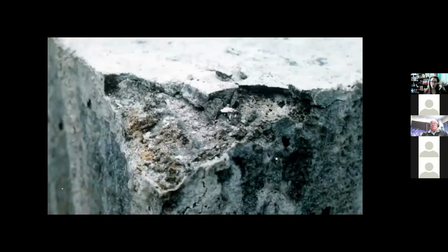We also can get spalls from exterior, not just trucks hitting things, but trucks overloading things. So whether it's a forklift or other thing, you can get what we call joint spalls and corner spalls of slabs, which is a shame because we can design to a higher end. And it's very important that we edge joint our structures and that, when necessary, we make sure that those joints are properly spaced so that they can give the ride quality and you want to transfer that load properly. So load transfer is very important to us.